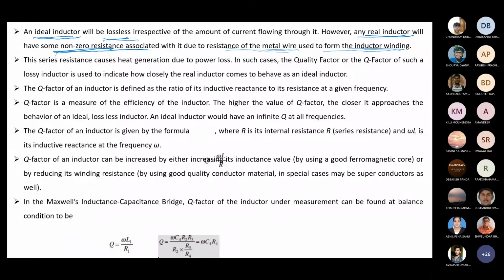The series resistance causes power loss. Definitely an I squared R loss will be there, an additional power loss that is not considered in normal cases. In ideal cases the resistor value tends to 0, but in the actual case the resistor is present.